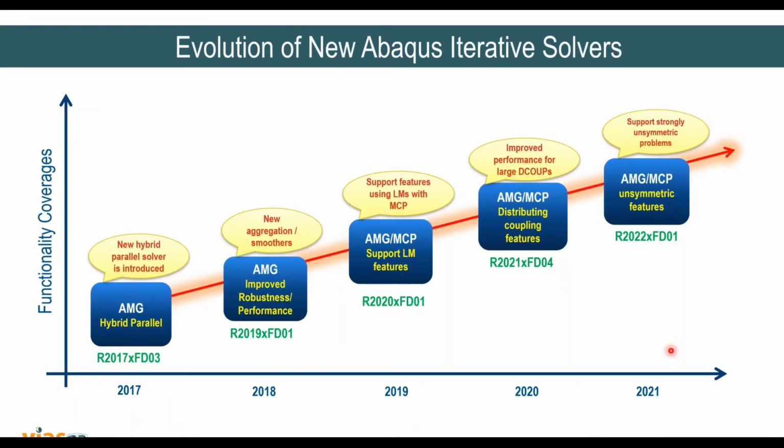We have some enhancements related to the Iterative Solver. So let me give you a brief about the Iterative Solver. This solver is typically used when you have a very huge model, multi-million degrees of freedom with relatively less non-linearity, which requires huge memory, and that's where iterative solvers are typically used to scale down the runtime, and these solvers have been improved over the various releases.